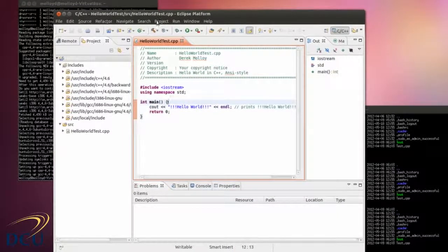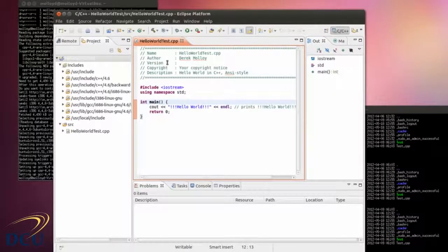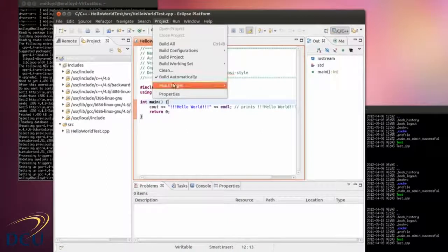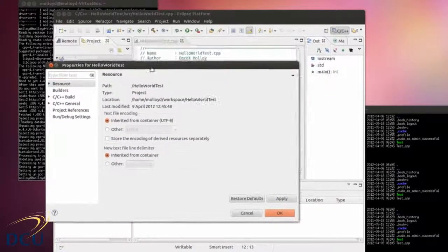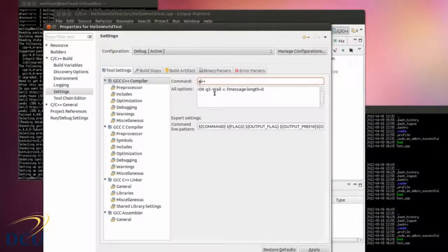So once we've installed this, now we need to switch out our standard Linux x86 compiler, and switch in our ARM compiler. So we're going to change our project settings. Select my project, properties, and I want to do a few things here. C++ build, settings. So my C++ compiler is going to be ARM, Linux, GNU, EABI, G++, sorry. And for my GNU C++ compiler, it's going to be that: ARM, Linux, GNU, EABI. Similarly for this. And finally for my assembler.